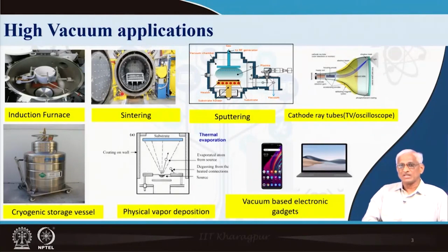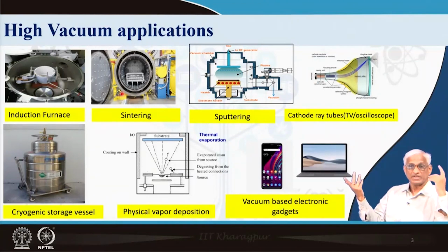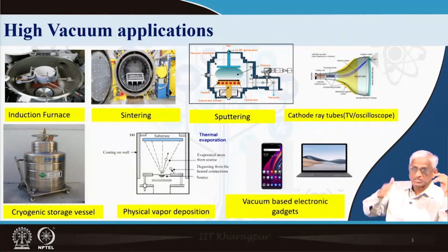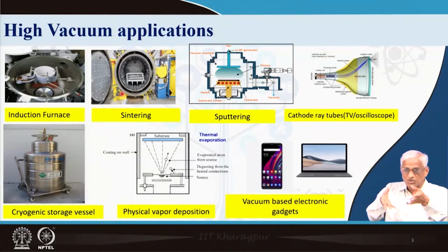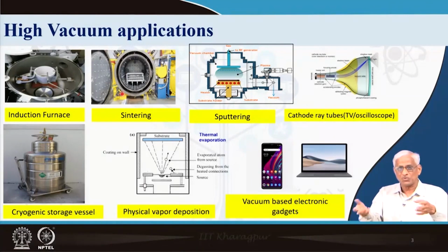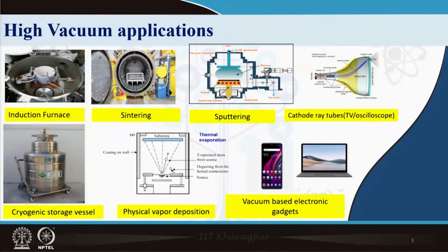But here metallurgical process conditions are always done at 10 power minus 6 or minus 7 base vacuum, and during process time, of course, the actual material when it is melting, its own vapors will come, which have to be continuously removed with high throughput pumps. So, during process, vapors may come and spoil the vacuum level, but it is not spoiling, it is only the increase in pressure.